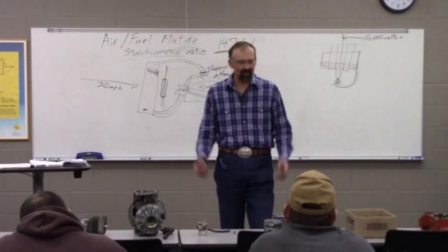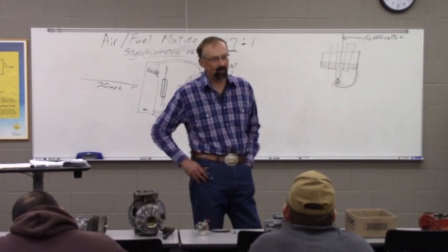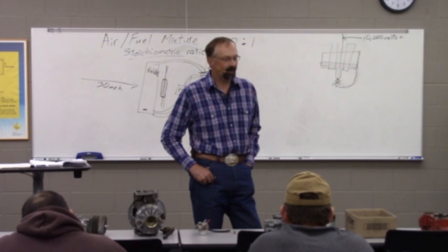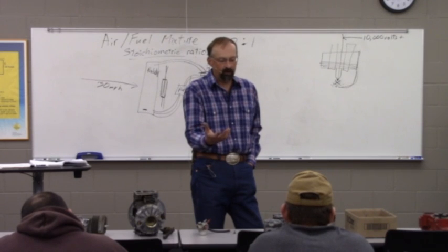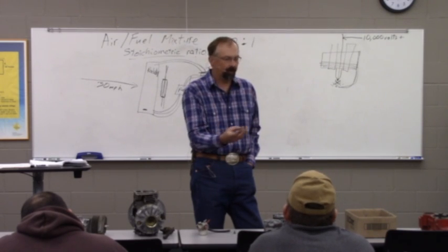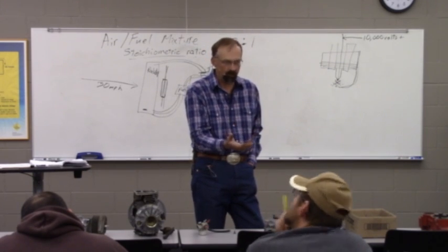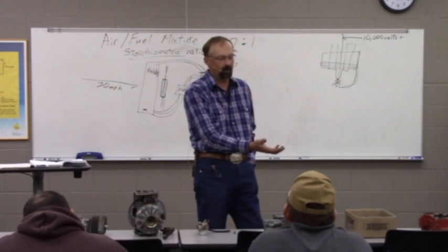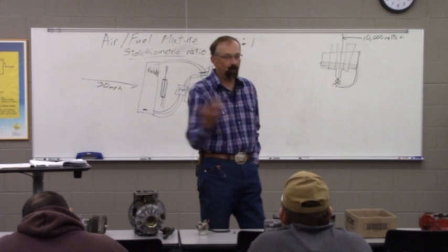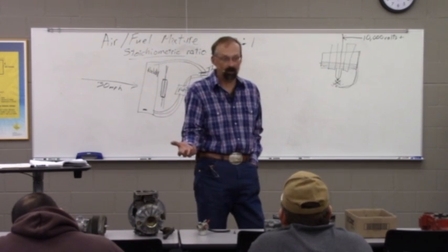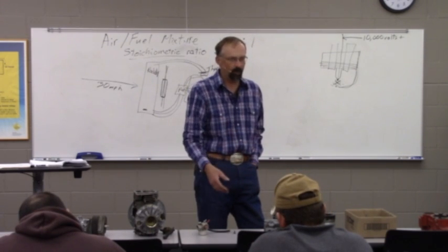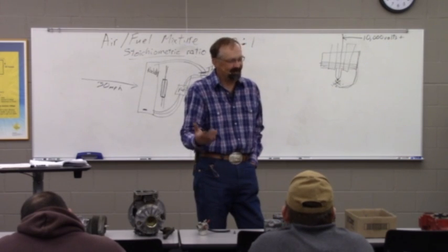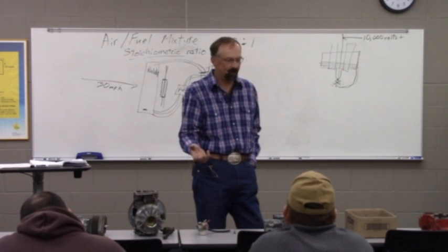We don't see a lot of benefit to the synthetic motor oils, because in most cases, even the natural motor oils, and I tend to live in the diesel pickup world, specifically the engine oil that's specified in a lot of those was the Rotella 15W-40 that was a natural mineral-based oil. And there are some of the newer engines that are specifying the T6 Rotella, which is a full synthetic. They make a T5, which is a blend of the two, and I don't really see the point of that. Pick one, but mixing the two, I'm not sure really gets you much of anywhere.